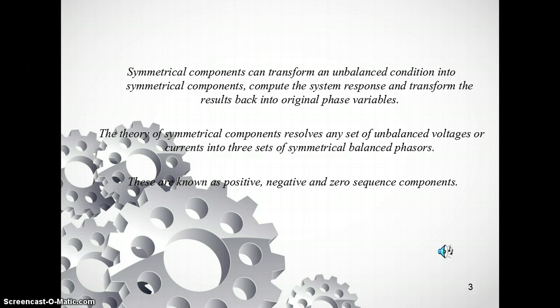It computes the system response by straightforward circuit analysis on simple circuit models and then transforms the result back into their original phase variables. In symmetrical component analysis, unbalanced three-phase voltages and currents are transformed into three sets of balanced voltages and currents. These are the positive, negative, and the zero sequence.